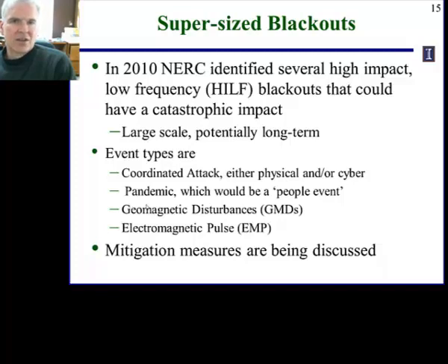These cause the transformers to saturate, and when you have a transformer being saturated, it tends to generate lots of harmonics. These harmonics can cause either rapid voltage collapse of the power grid or potentially heating in the transformers that could cause permanent damage to the transformers.